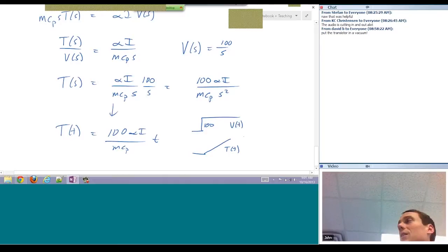So does that make sense? If you eliminated any convective heat transfer, would you have a ramp for that temperature? Would it ever get to a steady state value? Or would it just continue to ramp? Unless it melted, yeah. If it's perfectly insulated and the heat can't go anywhere, and your heat capacity is constant, it's going to be a linear ramp going up.